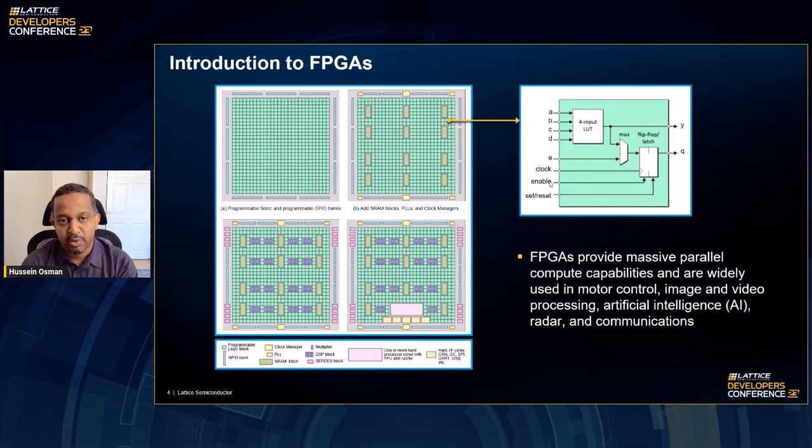The smallest logic resource on an FPGA is called a LUT, a lookup table, and it's basically a multi-input logic that can be defined, and based on the definition, an output would be taken out of the design. So in addition to SRAM, you see that there is DSP multipliers normally. Those are the purple things on the bottom left diagram. And then possibly a processor or some hardened I/O blocks like I2C, SPI, UART, USB, and so on.